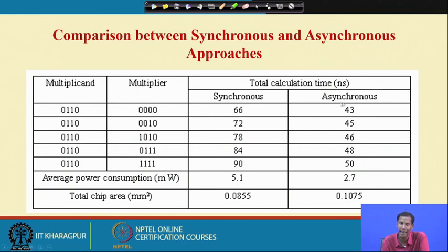In synchronous, in a particular clock it is checking the position of the LSB of B, then it does the shifting and count operation, and it also does the addition operation on the same clock edge.